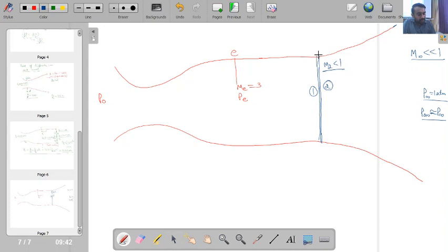So for the normal shock wave, I now know one parameter. First parameter is that PE is equal to P1. Pressure I am knowing at point 1. I am also knowing Mach number, M1 is equal to ME. So on the upstream of the shock wave, I also know Mach number. If I know the Mach number on the upstream, then I can predict the Mach number at the downstream. So if you calculate, M2 is coming out to be 0.475.